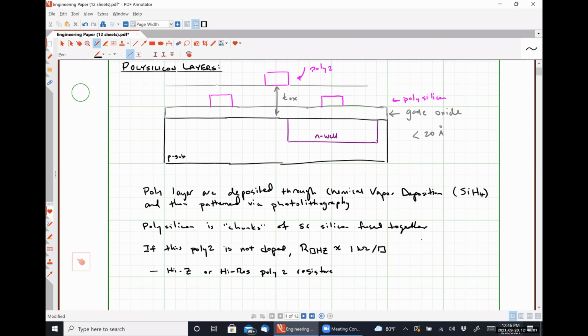So the thickness is going to have a potential gradient as well. And since that thickness has something to do with the resistance, effectively, you're going to wind up messing around with both the R and the C value, and they're going to be different at different points in the N-well resistor. For the poly 2 resistor, you don't have to worry about that whatsoever because there is no PN junction formed. So it's a uniform conductor through and through.